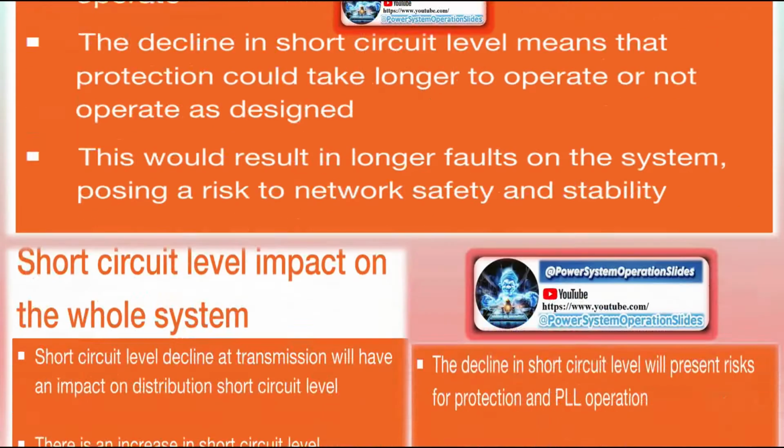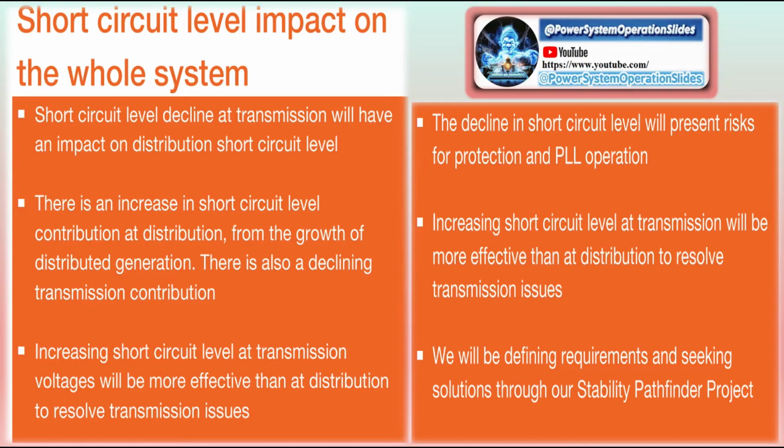The short circuit power is typically measured under conditions where the system is delivering maximum current during a fault, usually assessed during a transient state following a fault. In contrast, the rated power represents the normal operational capacity of the system under load. The SCR plays a vital role in assessing the fault handling capacity of the power system and can influence key aspects of system design, protection, and operation.